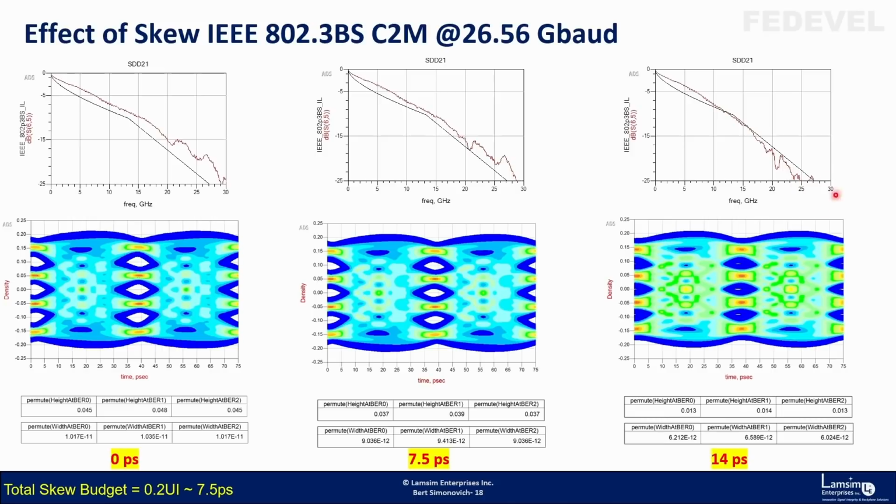And that resonance that was far out before is being pulled closer and closer to the 14 gigahertz. Even though you're not totally dipping at 14, you can see that the loss is now past this margin here. It's like, what, 17? No, it's about 12 dB. Down here, 13, 14 dB, and look what it's done to the PAM4.